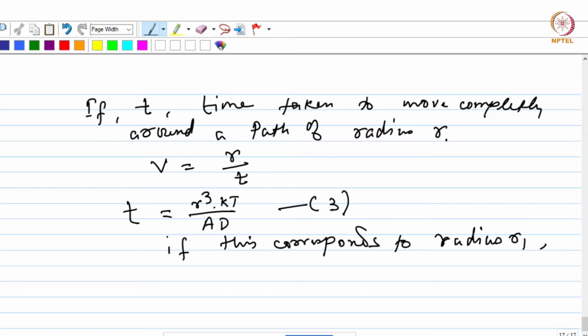So now if you consider a small time increment dt and see the accumulation or movement of solute atoms over this time increment, in this time increment, each of the flow lines will add a number of solute atoms to the dislocation, and therefore you can expect the length of the dislocation line to increase.